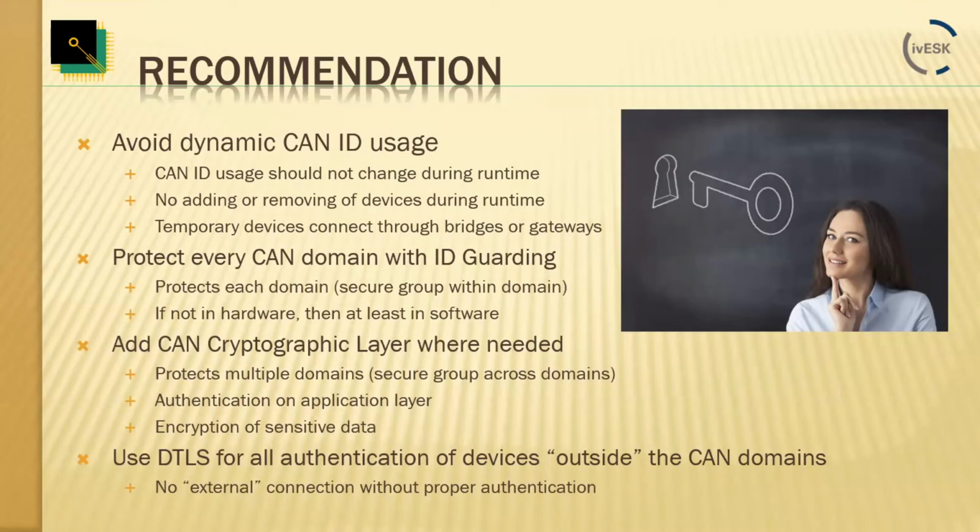However, there are some CANopen profiles and systems where those can change during runtime. There's some authority out there that can say, oh, device number 5, for this purpose, you can now use CAN ID 234.